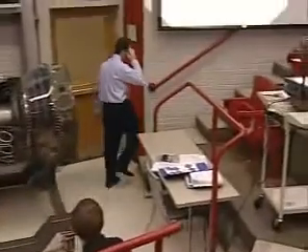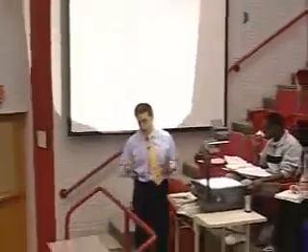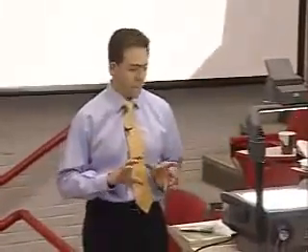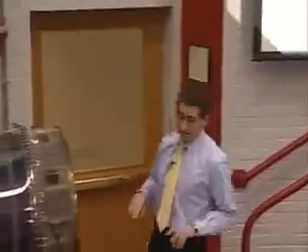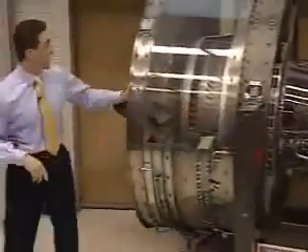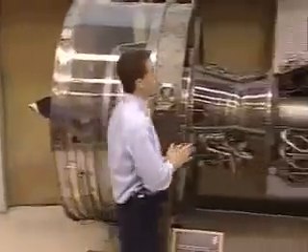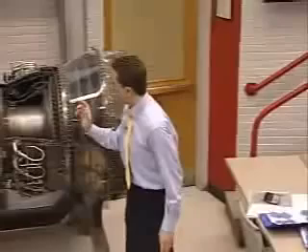We've got a challenging lecture today because probably the most complicated bit of work to do conceptually is our last lecture in propulsion. And the basic objective of that lecture is to, again, show how the moving blade rows in this engine can change the stagnation temperatures, change the stagnation pressures, and then connect that to cycle analysis, and then connect that up to mission performance. So this is the last bit.